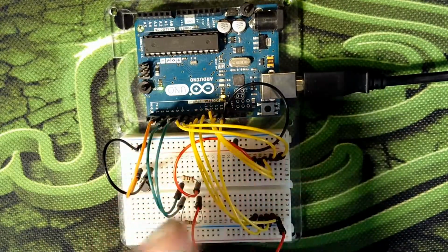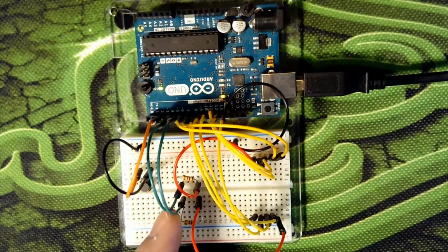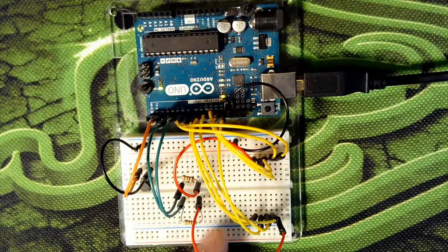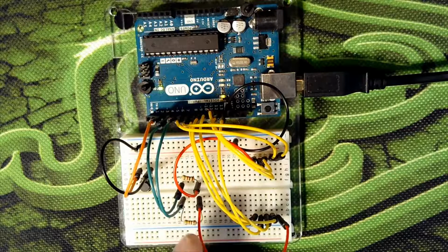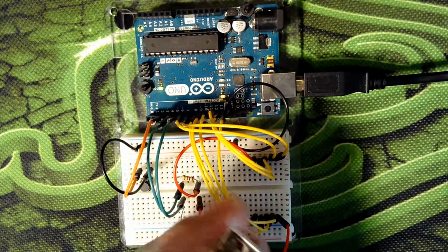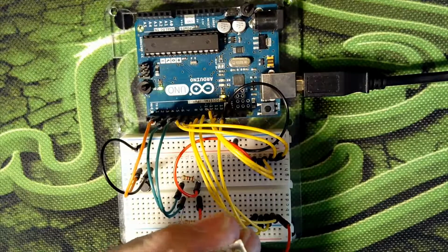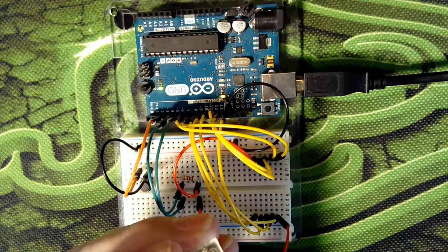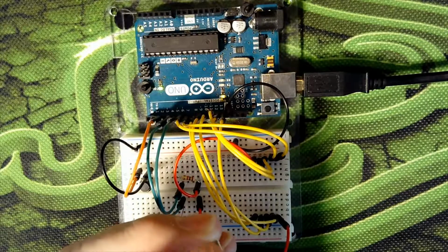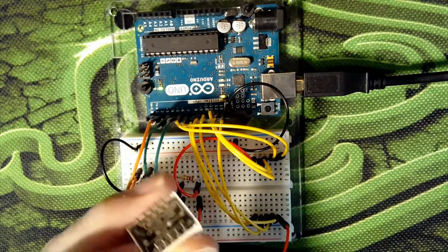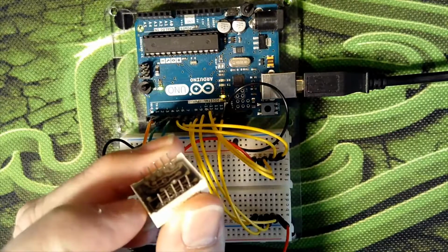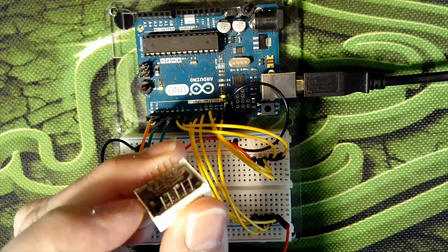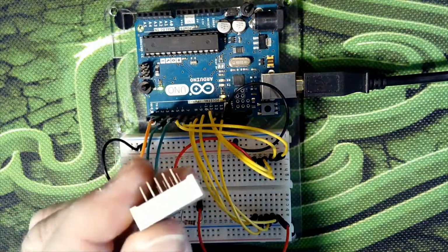And all I do is, using the resistor, I connect one side to power, and I connect the lead off of it to use as a jumper, like this red one. And then I hook one to ground, and then very carefully I go from one pin to another, and I see what lights up until I figure out which one's the common and for which segment. And then I can figure out which one's A, which one's B, which one's C, and I can work my way around just attaching it to those different pins until I get happy and see where it actually works.